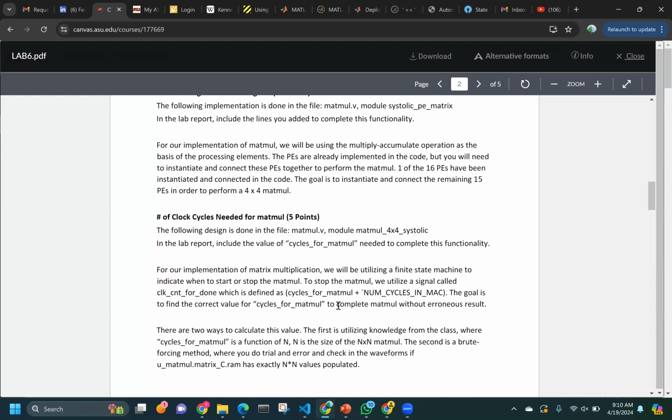Similarly, in a systolic array multiplier, your products or partial products are moving in a certain systolic fashion, and that is why the name of the architecture. That essentially means that only after a certain number of clock cycles you can see the real output. Before that, all you see in the test bench or in the waveform are your partial products.